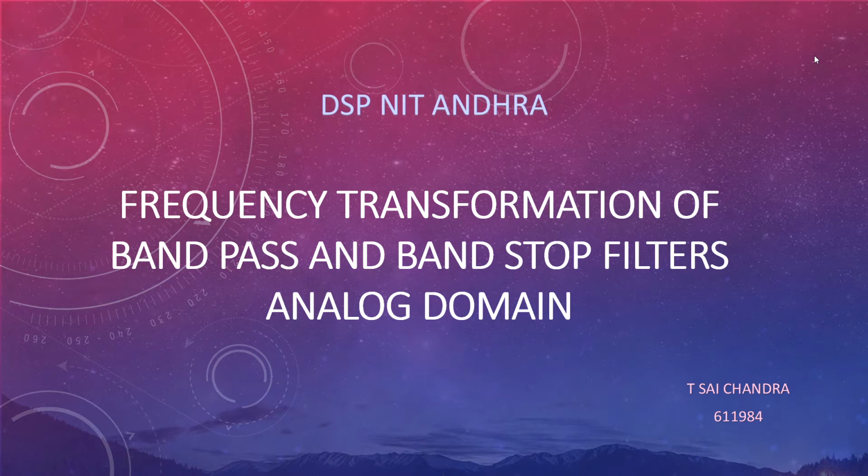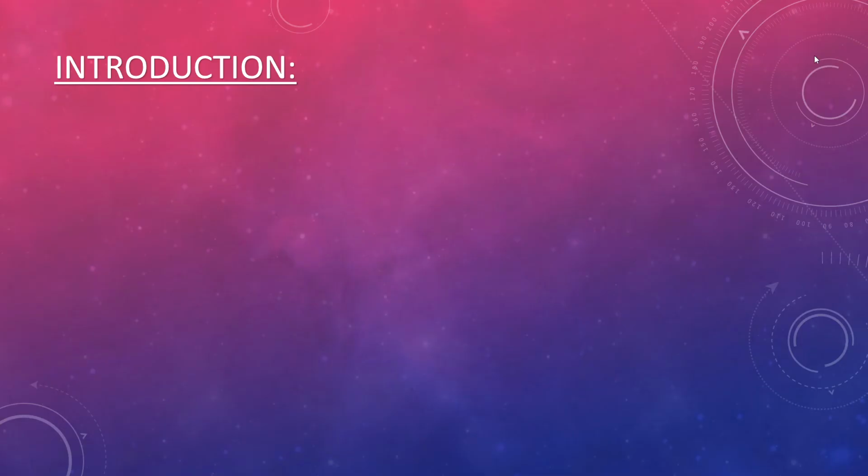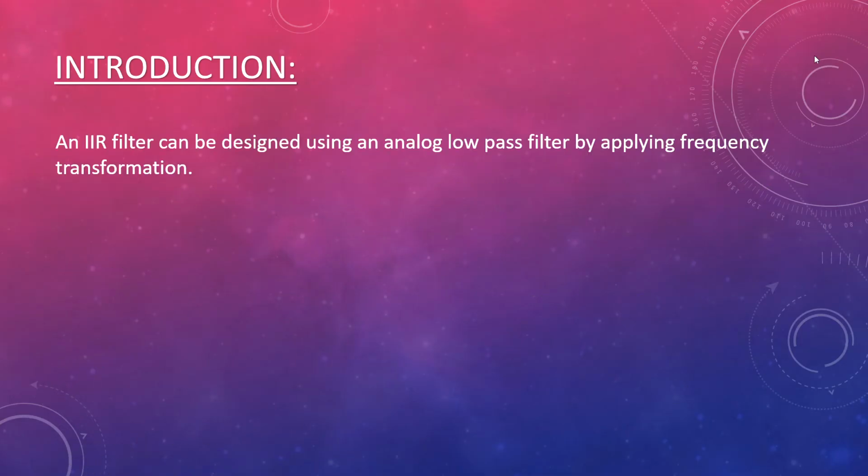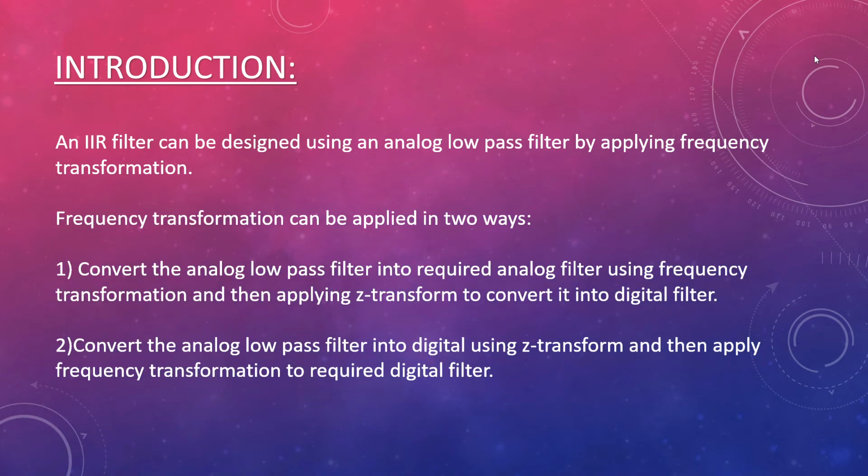Today we are going to discuss frequency transformation of bandpass and bandstop filters in the analog domain. We can design an IIR filter using an analog low-pass filter by applying frequency transformation. Transformation can be applied in two ways.